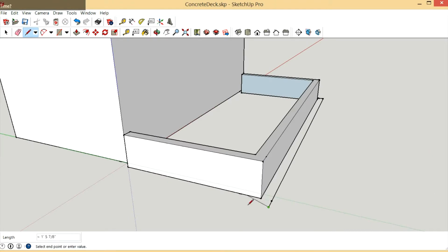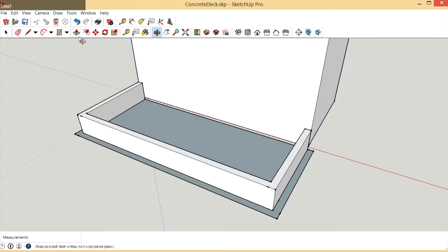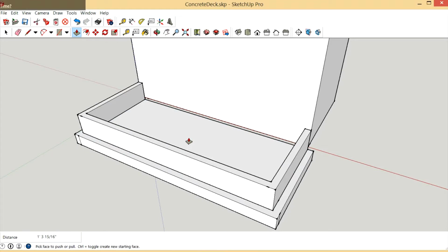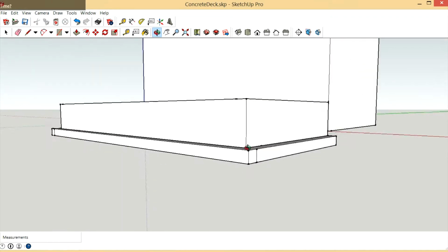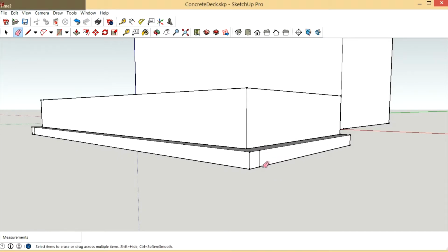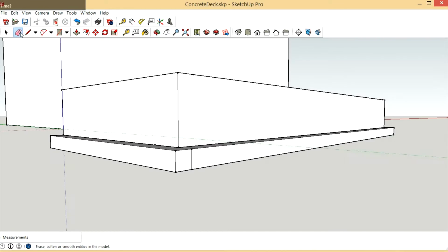I'm doing this this way on purpose to show you how easy this can be if you want it to be. And so now I'm going to take this around back to here. I'm going to make the footing a foot deep. It could be 8 inches if you have the proper soil types or whatever, but I'm going to make that 12 on my drawing because I like to make them 12. I just like them thick.